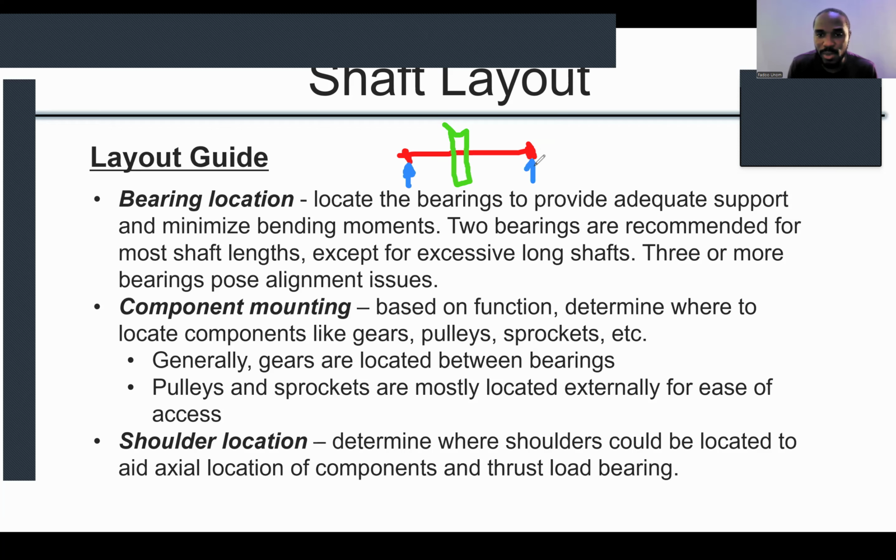They provide support at that point, right? But this gear that I've placed here has a weight that acts downwards. So the tendency of this shaft is to bend like that. So bending moments cause a shaft to bend.